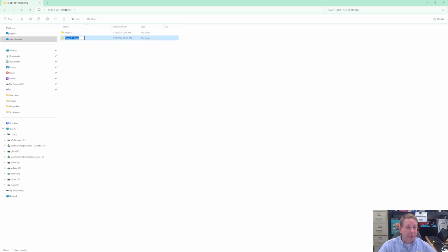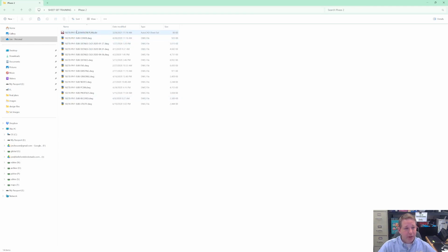We got a copy. I'm going to rename that folder. We're going to say phase two. Open that up. Nothing has changed in here. Now, I would recommend that if you are in here already, you can go ahead and rename the sheet set, the DST file only. If you change that to whatever phase you're at, that's the only thing that you need to change your name in at this time in Windows Explorer.